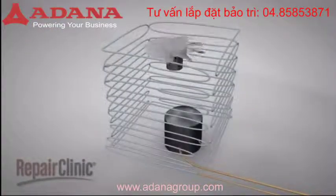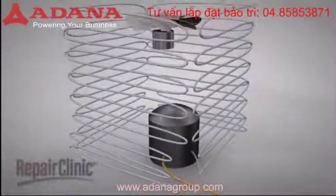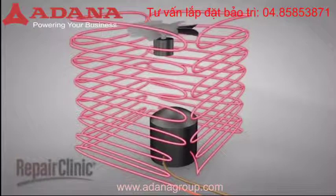The compressor acts as a pump, compressing refrigerant in gas form into the condenser coils, where the gas is condensed into a hot liquid. The condenser coils dissipate the heat as the liquid travels through them, and a fan is used to assist the coils in this process.